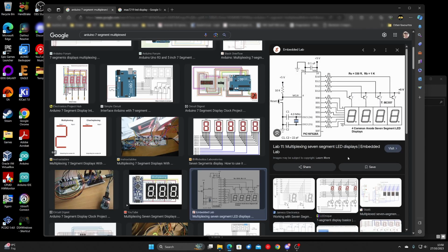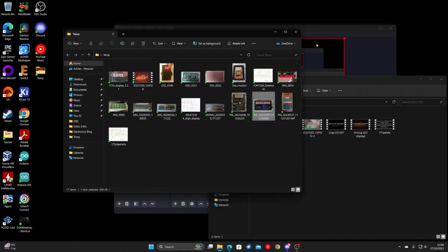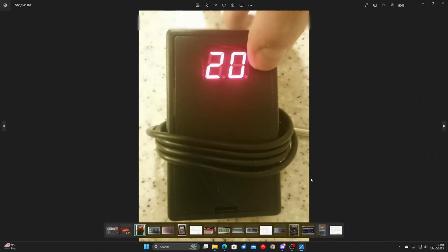It's the same thing when you're using a PIC microcontroller, but that's using common anode displays. You can see how many pins it uses. It's maybe for 2 or 3 digits. Again, I did use that method on one of my projects, which is this here. This little gadget. It provides roughly 5 milliamps of current per segment, and the displays are multiplexed, so it's switching between the two. The current limiting resistors are set to put 10 milliamps through, and only one of those digits is on for any one time.